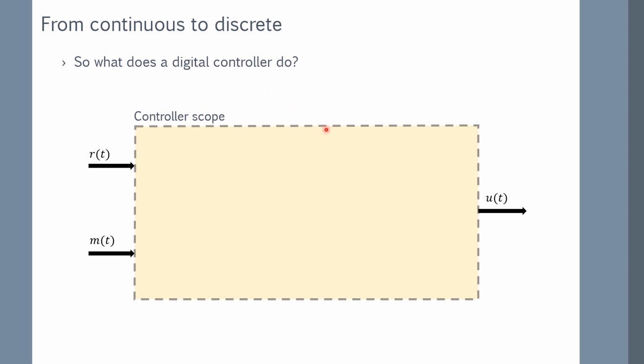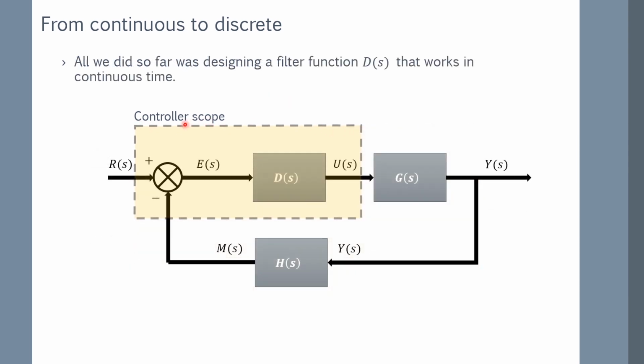So what we want to do is fill up the box, basically. Let me just go back here. This is just a closed loop control system, and you can see that we have the standard nomenclature where we have a control input. We compare the control input with the measurement. We get an error. We apply a control law to this error, and then we get an output that goes to our plant, whichever plant it is. It could be a motor, a tank, a heater, or whatever. Then the plant does whatever it does, and it changes the control variable. The control variable goes back into the measurement device. The measurement device is also not perfect, so it also has its own transfer function, H of S.